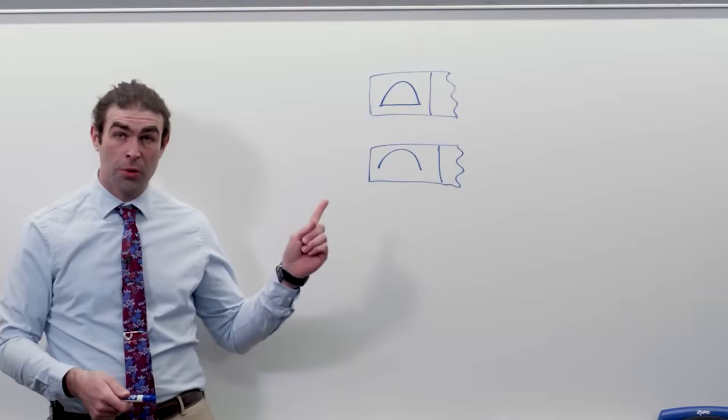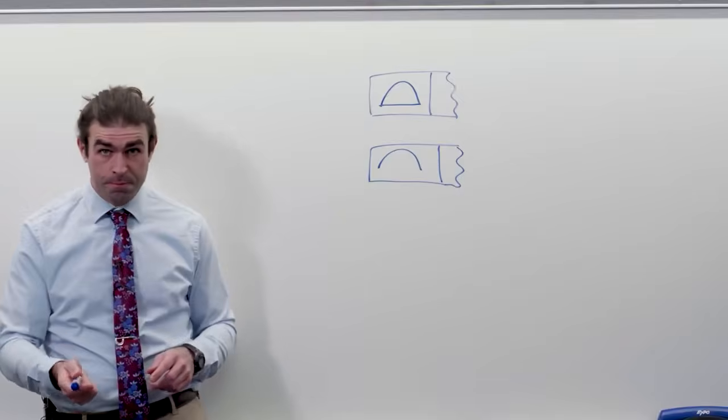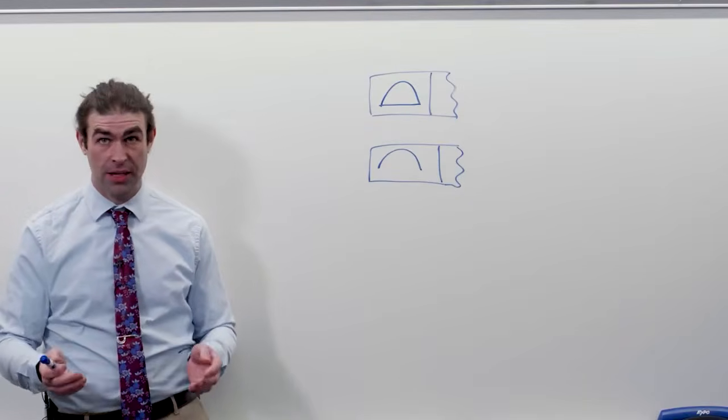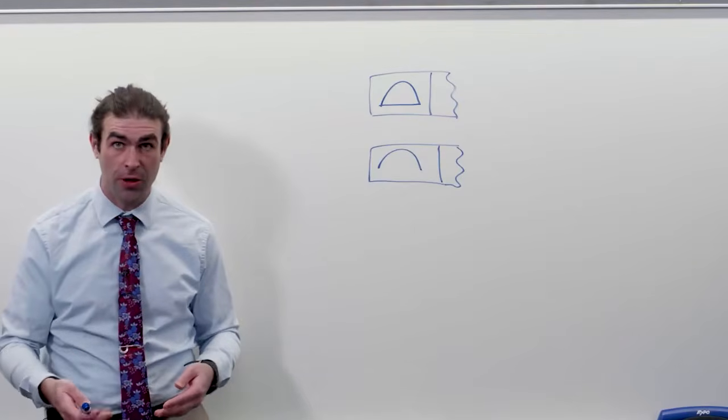Profile works in a similar way. The big difference, and I'll explain more about this in a minute, is that profile is not limited to flat surfaces like flatness and things like parallelism are.